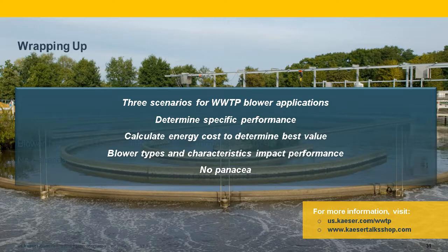Air temperature affects both air density and blower performance. What do you recommend as an evaluation for inlet conditions? Well, your inlet conditions, ultimately you have to pick something. A lot of people will use what they call ASHRAE data, where they type in their location, and ASHRAE will give you the most representative temperature for your location. That will include your elevation, your humidity, as well as temperatures.